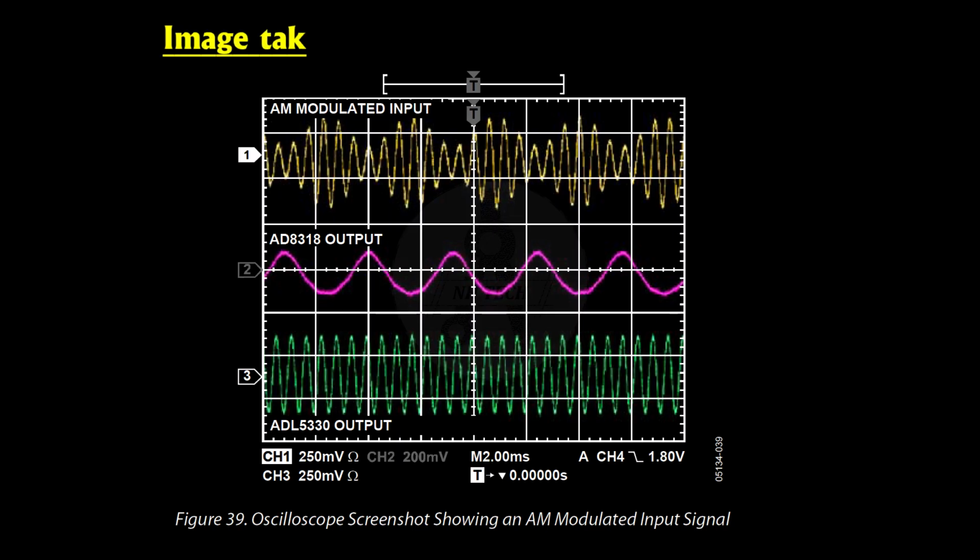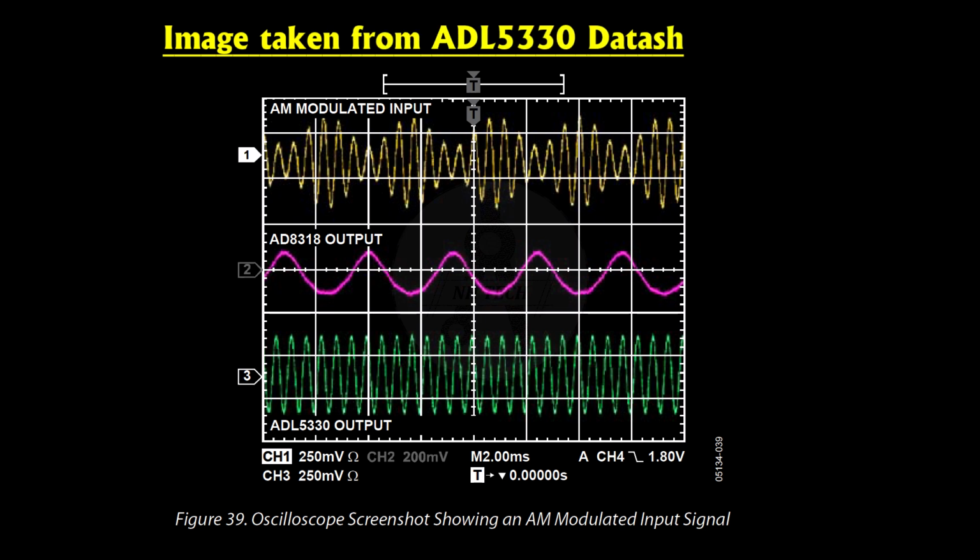So overall, AGC plays a critical role in ensuring reliable signal reception by automatically adapting the system to changing signal conditions. It allows the receiver to make full use of its dynamic range, prevents distortion from strong signals, and ensures that weak signals are still detectable.